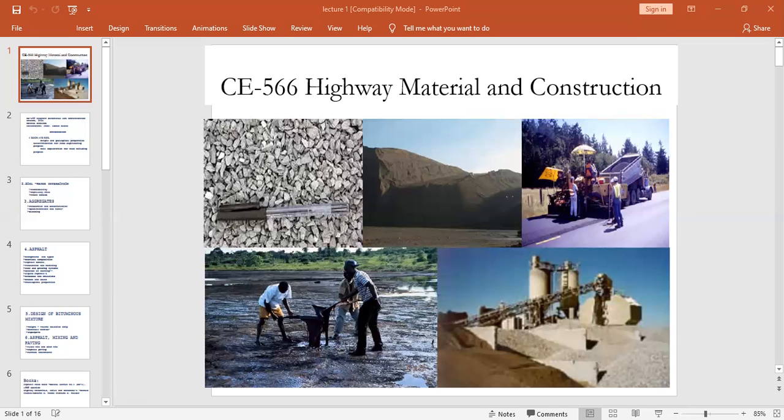The joint at the end of the day, or if, say, the weather changes, and rain starts falling beyond a certain limit, then you have to obviously close the road. There we have a construction joint. And obviously there are ways to do that, but normally you don't have a transverse joint in the pavement.